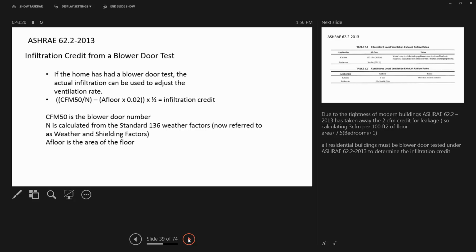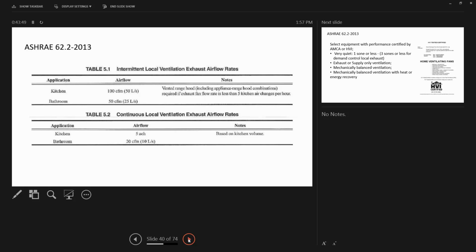We'll go through these calculations a little bit when we go through conductive heat loss and minimum ventilation guidelines. Based on how tight the home is, you can come up with a recommended minimum ventilation. So don't worry about this yet, but you'll be able to do that calculation. When we do our REScheck on our sample house, we're going to play with that a little bit and come up with a couple of different building envelopes, and some are going to be tighter than others. The tighter the building envelope, the more mechanical ventilation we're going to need. Just know that it's all set in code.